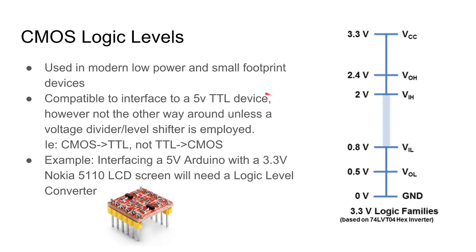And one nice thing about it is that the CMOS logic levels are able to interface with 5-volt TTL devices. So they have a backward compatibility feature built in, which is really great, and it makes it easier for designers to use modern devices with older devices.